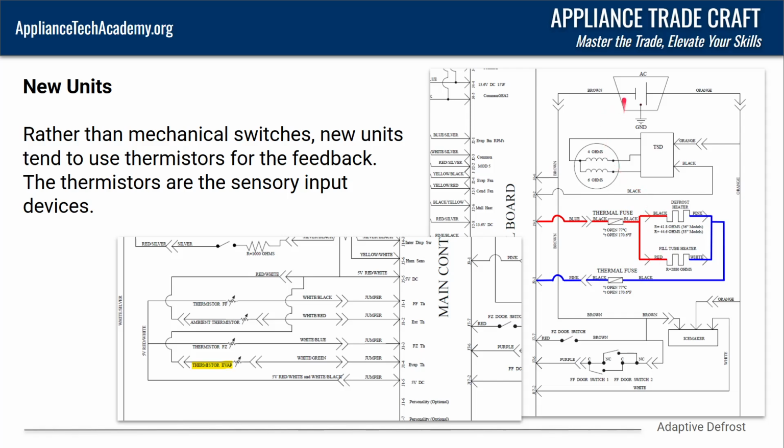And then one final thing, if you're looking at this, we got our AC voltage coming in. Let's assume this is our line voltage. Comes in, comes down, branches off to the ice maker. So on this one, looks like a standalone ice maker. It gets 120 volts, makes its own decision. But it also branches off and comes down here, branches off again. We come right over here, freezer door switch. Comes over here, branches off two times more, so it looks like it's got three door switches that are going to make some motion on this.